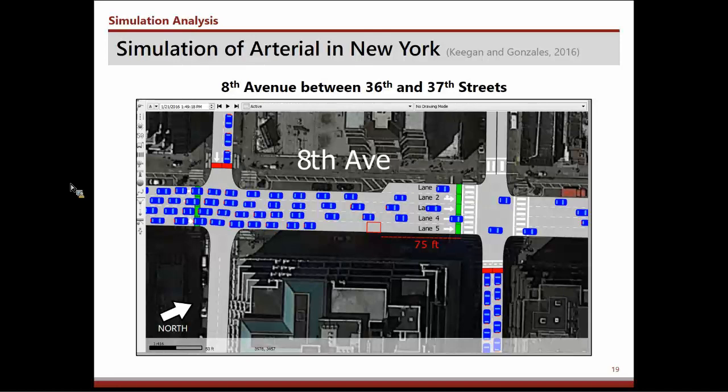So in the case that we had heavy pedestrian volumes, maybe without pedestrians, we could have gotten 15 or 20 vehicles making a right turn, but in reality, only 4 or 5 got through. So in that case, we went into the parameter settings of the simulation and calibrated them to represent realistically the saturation rate that gets through the intersection on the green in the through direction and also for the turning movements.